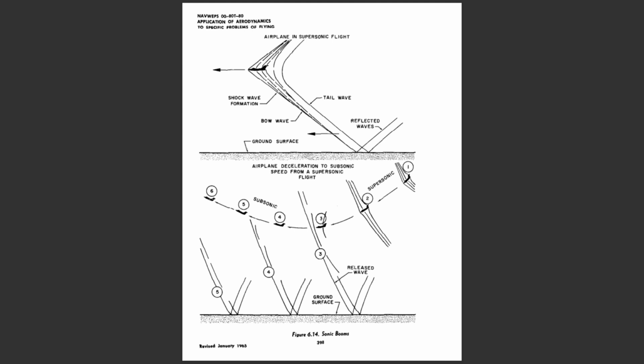When the airplane slows to subsonic, the shock wave travels out ahead of the airplane in a form which is somewhat spherical. Because there are density variations through the shock wave, the wave moving ahead of the airplane can cause aberrations in light waves, and it may appear to the pilot as if a large sheet of clear cellulose or plastic were in front of the airplane. In addition, the density variation and initial shape of the wave leaving the airplane may cause reflection of sunlight which would appear as a sudden, brilliant flash to the pilot.